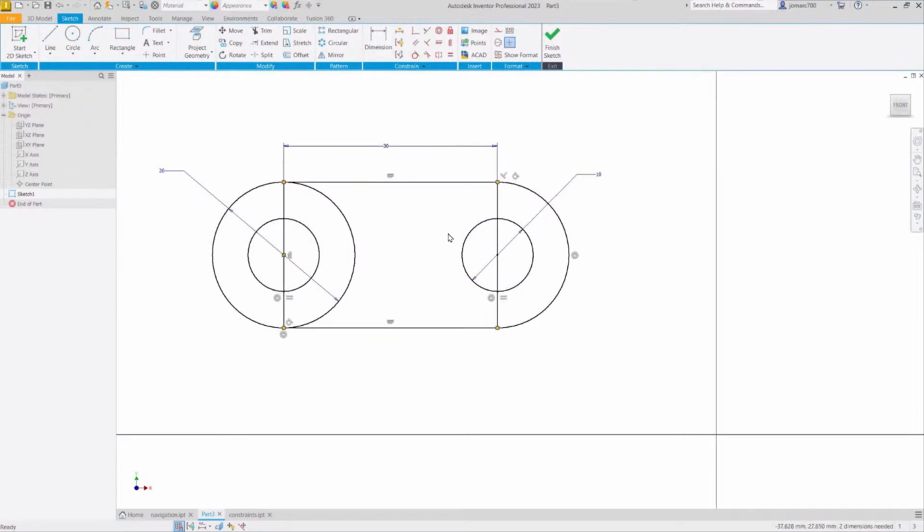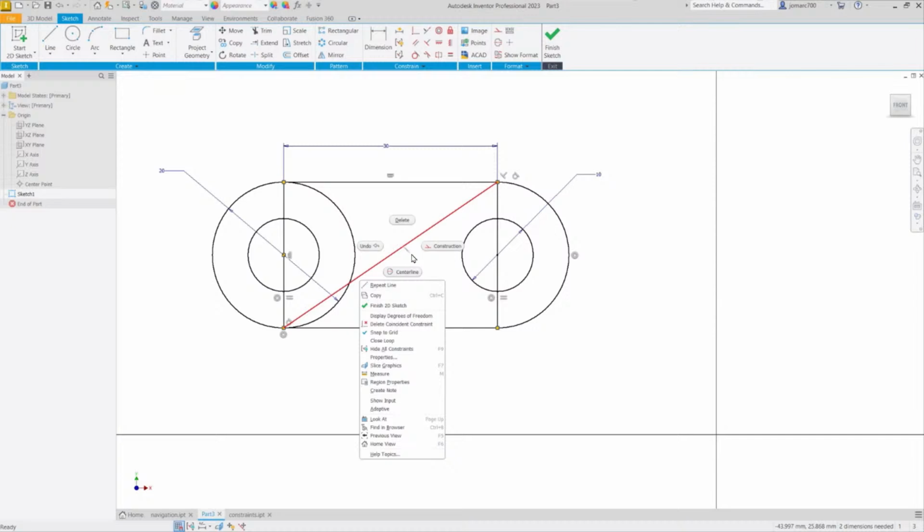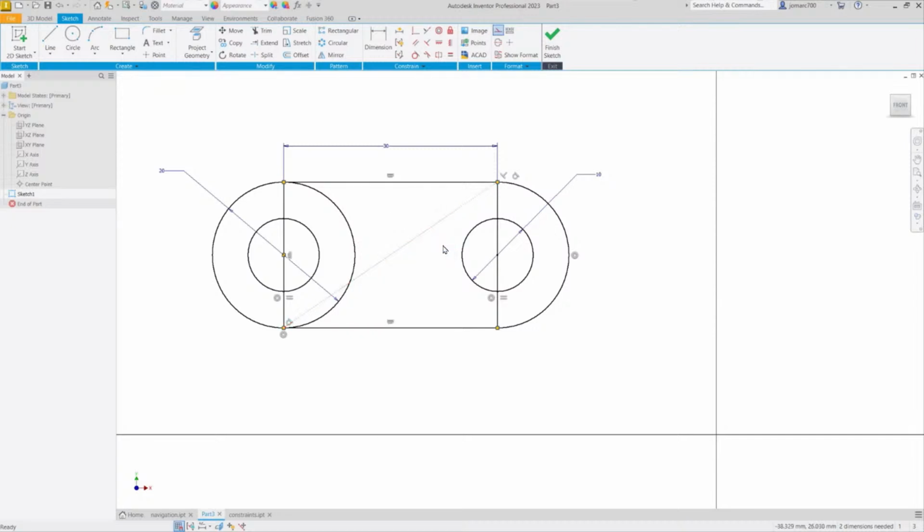And for the center of the sketch to be aligned with our center point, we need to create a new entity. And that entity, I am seeing it should be a line. So I'm going to hit L for line, creating a line from this point, left click here, moving up to here, double left click, hitting escape. Because this line serves as a construction line or helper, I'm going to select this, right click, and turn this into a construction entity.